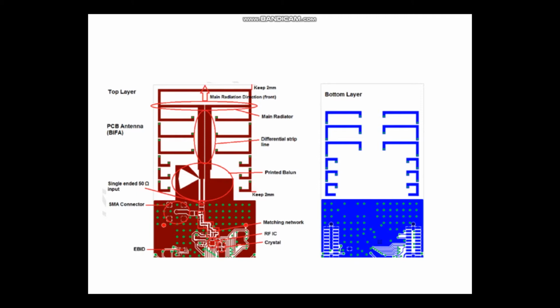This is a three-dimensional design, so we have the top layer, as mentioned here, bottom layer. So the whole of all of this architecture here is actually antenna as well, and it's a three-dimensional design that goes down in this bottom layer, and so it kind of curls around here, and that generates a larger overall electric length. And keeping in mind that in between this 1 millimeter thick layer is this filler stuff, which is the PMMA dielectric.